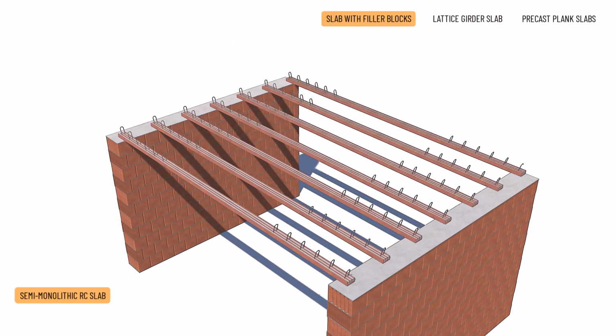The joists are pre-stressed. The low-height base, 6.5 centimeters, consists of a reinforced concrete core and a ceramic shell underneath. From this, the stirrups project every 25 centimeters. The joists have an axial spacing of 45 or 60 centimeters, and the required bearing length is a minimum of 12 centimeters.